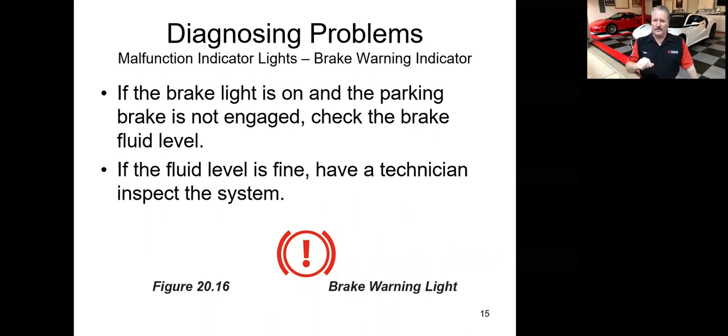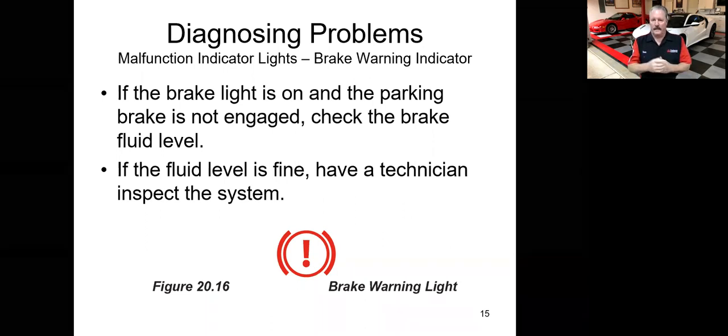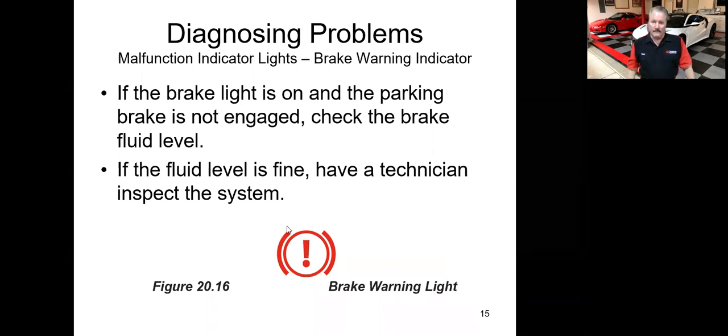If the brake light is on and the parking brake is not engaged, check the brake fluid level in the master cylinder reservoir. It might be a little bit low, and there might be a sensor there that is seeing that the fluid is a little low in the reservoir, and it'll trigger this light. So if this light comes on, we need to start looking at the brake system. If the fluid is low in the reservoir, then we might be getting near the time of needing brakes on the car as well.